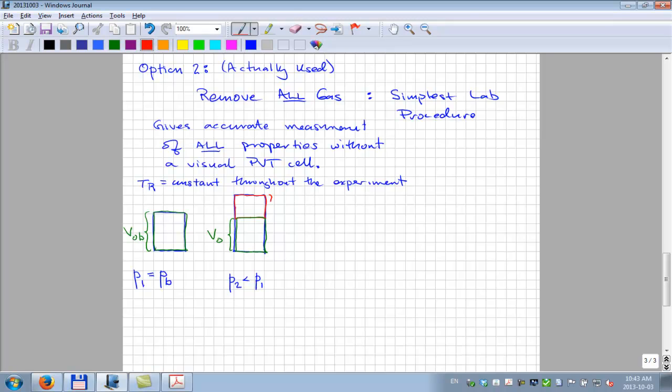We will know how much gas is taken away because it's taken away, all of it. We'll then know what's left in the cell because that's only oil. We'll also measure the moles of gas that have been produced.